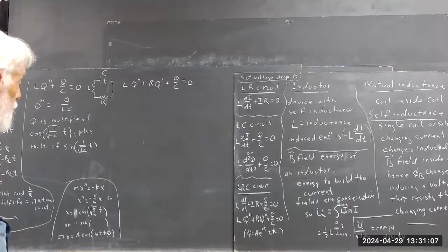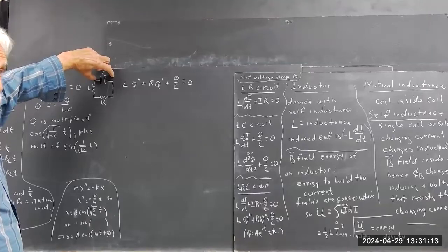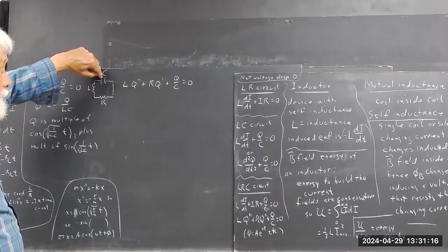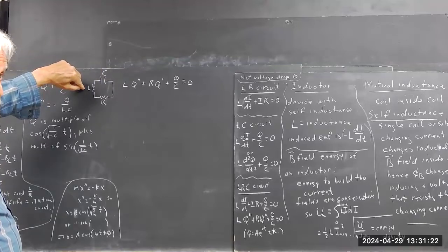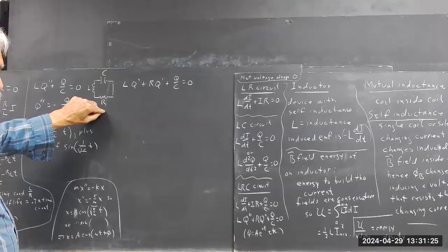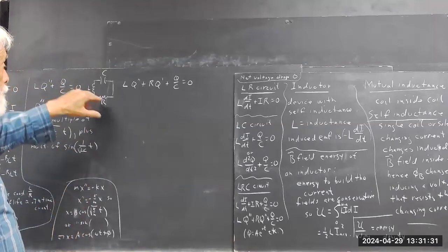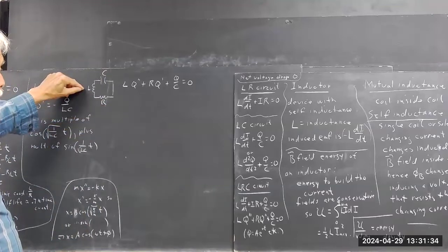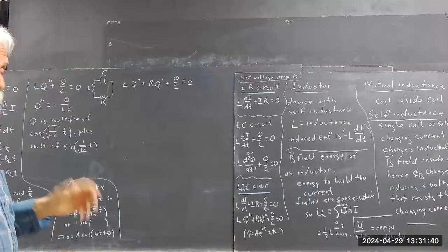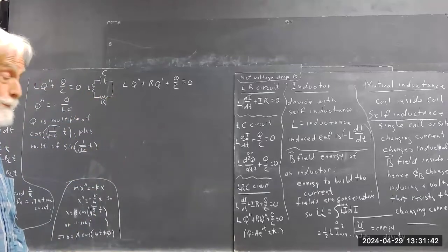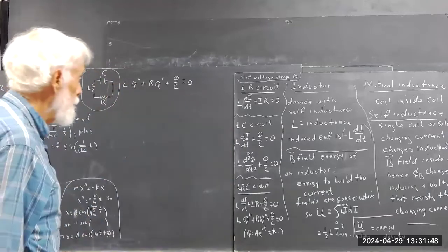So one way to get a current in the thing is something you understand. You charge up the capacitor, then take the clips off. The capacitor is going to discharge, which tends to increase the current in the inductor, limited by the resistance, and maybe this is the resistance of the inductor. Okay? So you could only go so fast because of this, and even slower because you're increasing the flux within the inductor, which fights the increase of the current. All right. That's what's going on. And this equation tells you how that all works out.